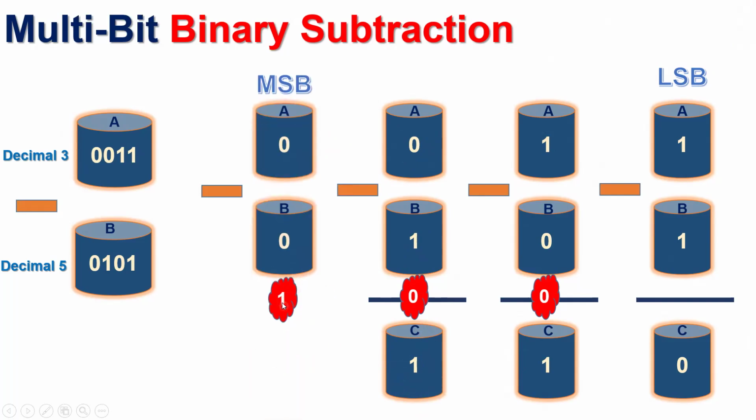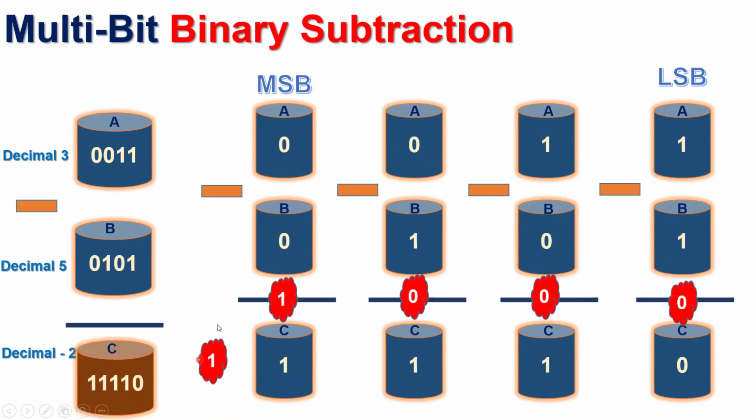So we'll write here borrow in. The final bits, MSBs of A and B, 0, 0. And final subtraction at this bit position we'll see 0 minus 0 minus 1. Again, you have to borrow 1 from the next position. If there is any bit to borrow from, there is no bit here, but the difference therefore will be written as 1 and the borrow out will be 1 and it will be written just to indicate sign.